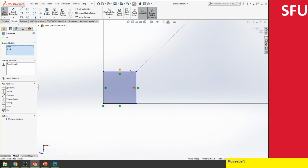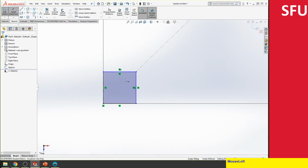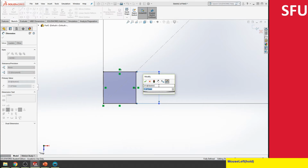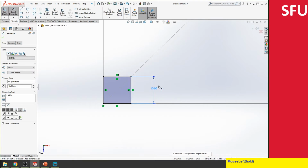The other option would be to make this line and this line perpendicular, which would kind of achieve the same objective here. So once you have that, we can give a dimension for this. So maybe we call this about 10 millimeters. I could have, instead of giving the equality constraint, made this line and this line both equal to 10 millimeters. So it will kind of do the same thing.